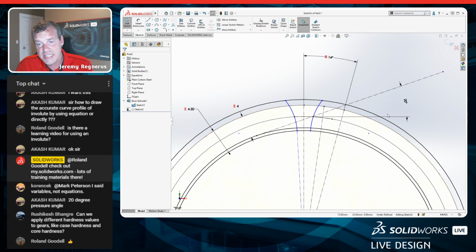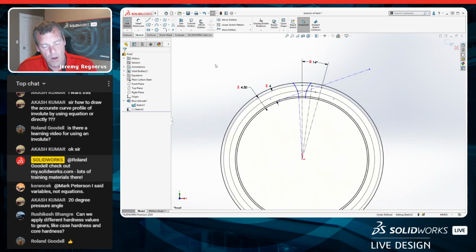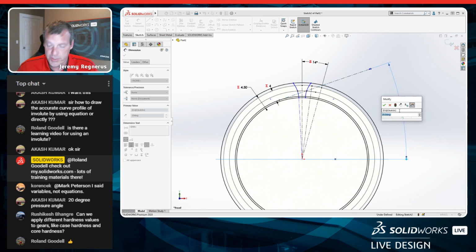But that requires me selecting that geometry. Here's another cool trick. You can always dimension to geometry even if it's hidden, if it's selectable. So for example, because I'm looking normal to my gear, I can dimension to this top plane. Well, from a top plane view, that is a line. And then I can dimension that to that sketch and get my 20 degrees right there.